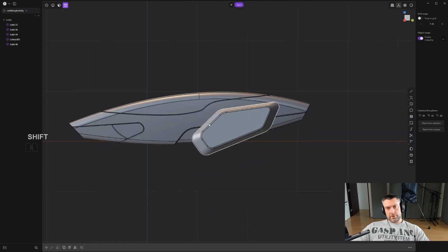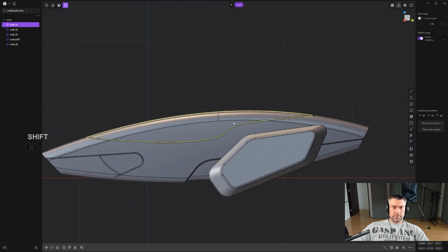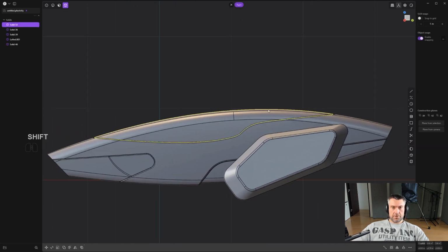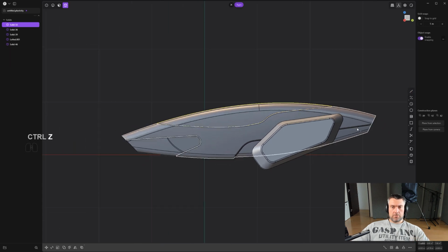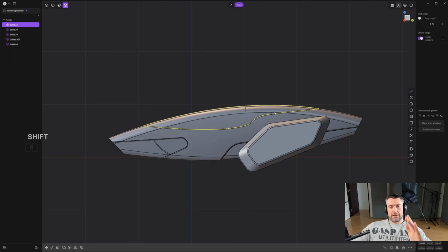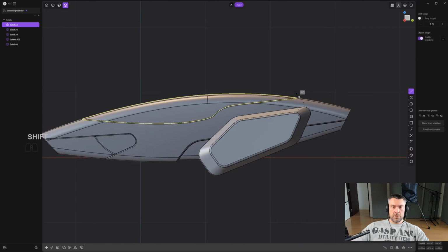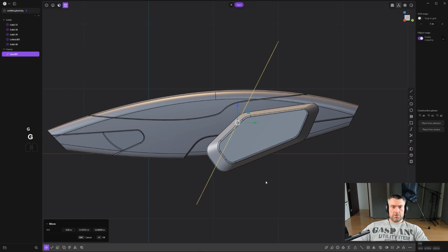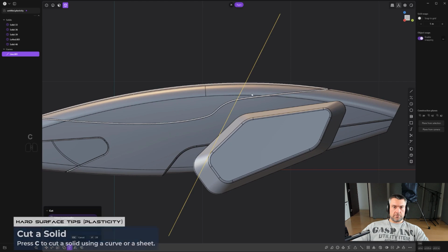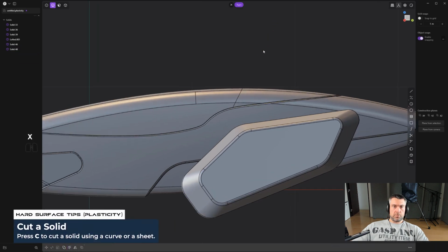So now, in addition to all this, we're going to split the back here. When you're texturing, you're going to have a separate section. We could just simply slice it here, but we could follow an angle, echoing the angle from other elements. So we could follow this one, for instance. Click here, then tap Shift like this and run a line on this angle. We're going to move a gizmo somewhere here, and we're going to slice it. So C and slice it, right? Now we have two parts here.